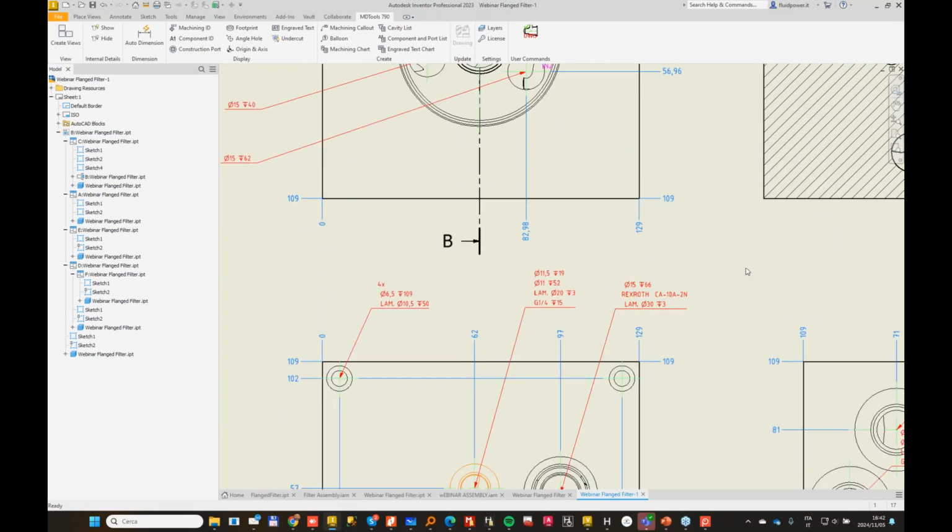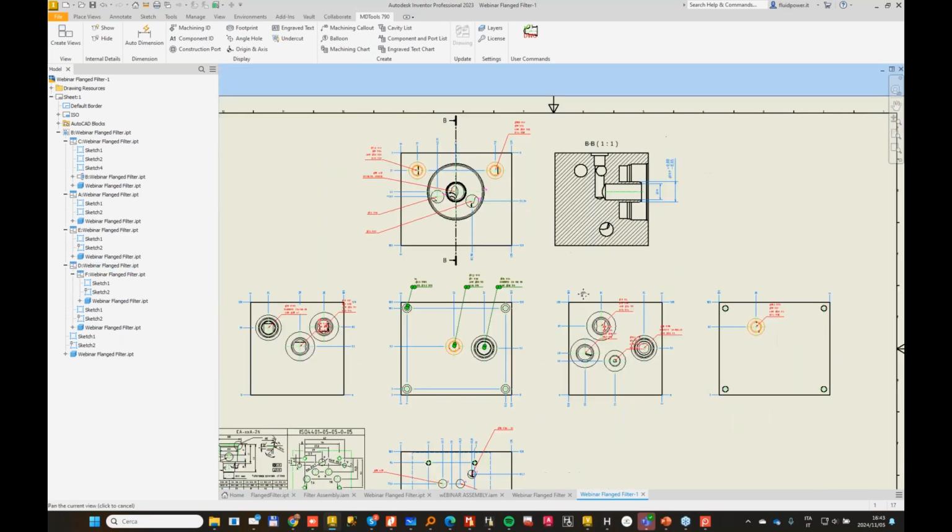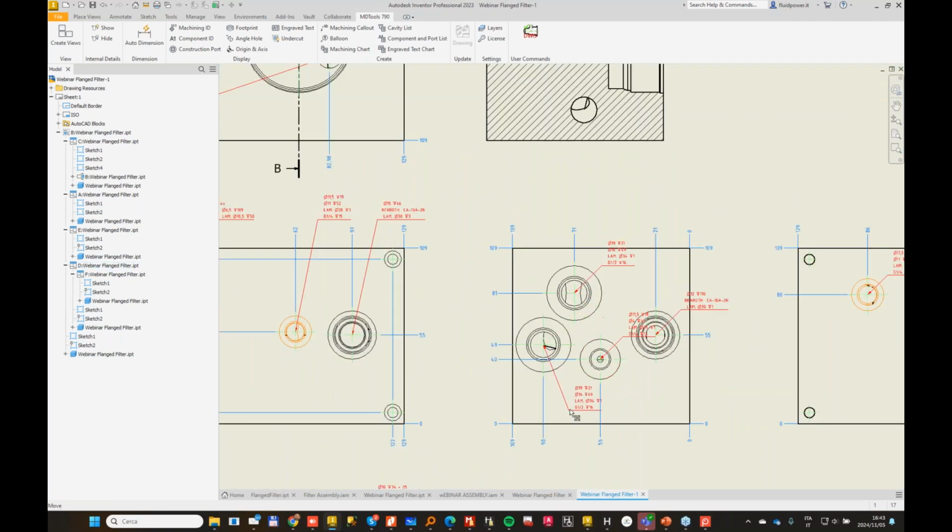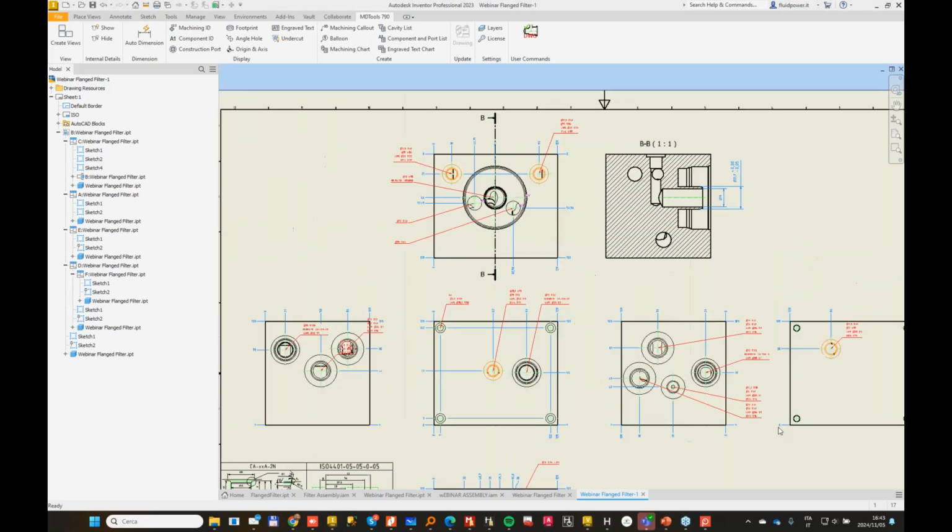For those using Inventor, a technique to keep good alignment between letters: select, right-click, align vertical or align horizontal. So if you need to align horizontal or vertical, you just select, and then it will be easy to give a good alignment. Like in this case, you can just position randomly, like here, then select all, align vertical, and move the text all around.